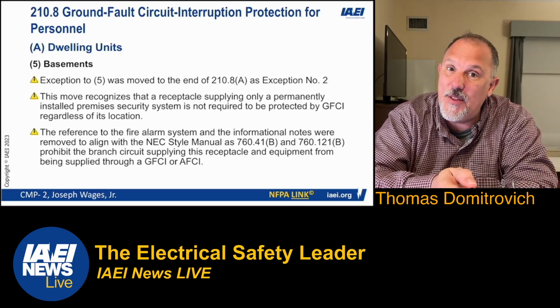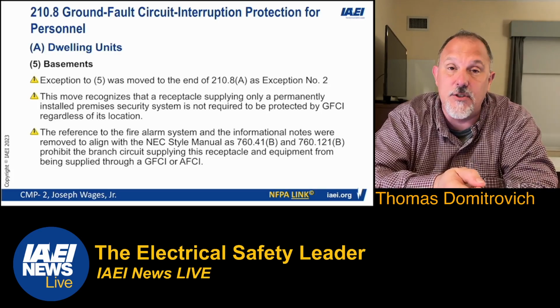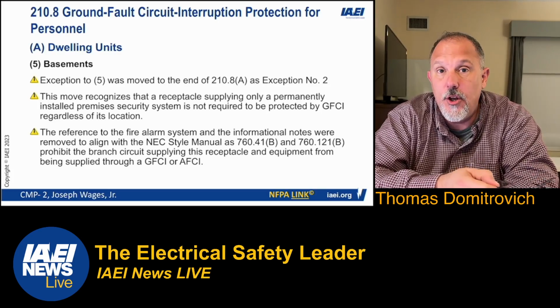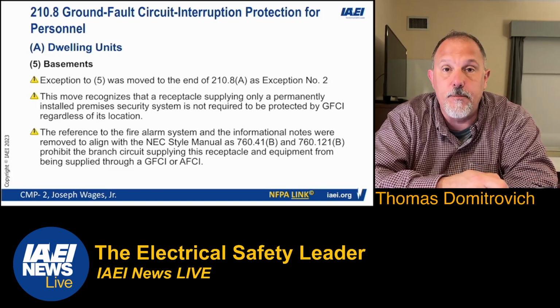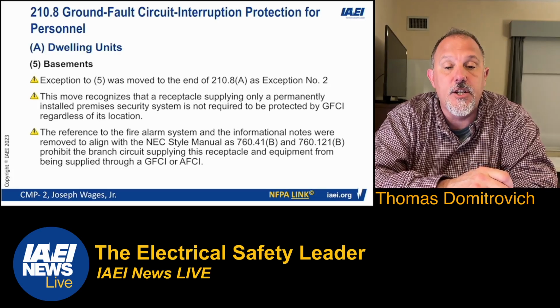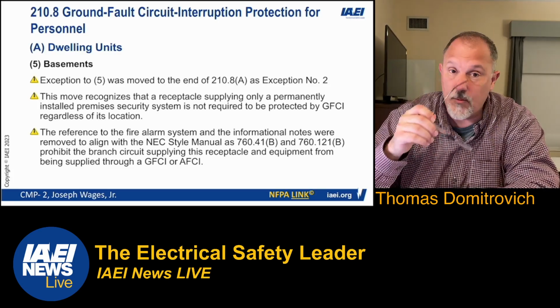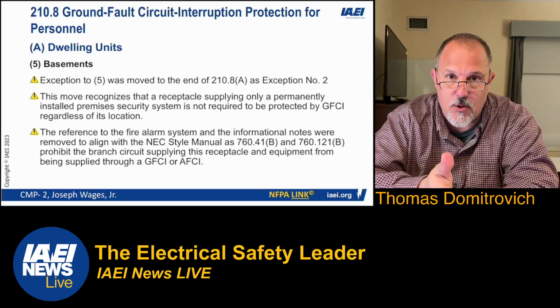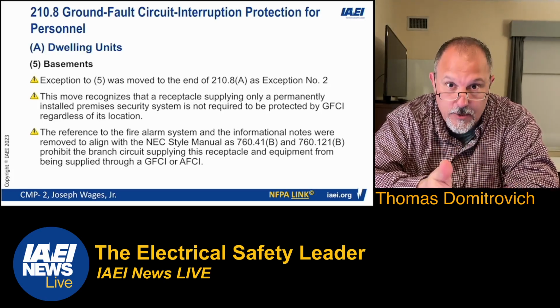But we could not do that for the burglar alarm system because there's no other requirement in the NEC that says you shall not put your burglar alarm on a GFCI. So what we did was we didn't call it a burglar alarm system because NFPA has requirements for security systems.